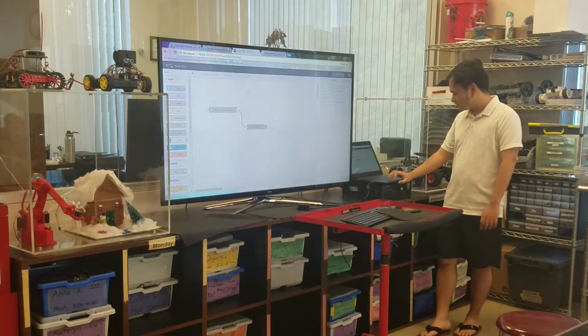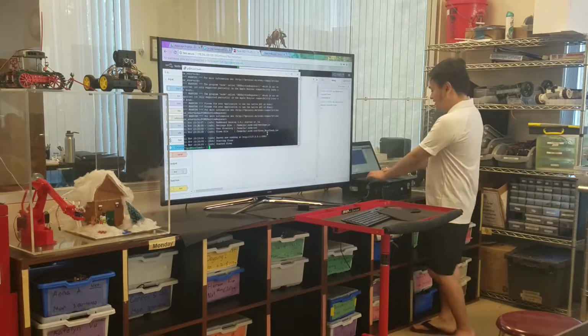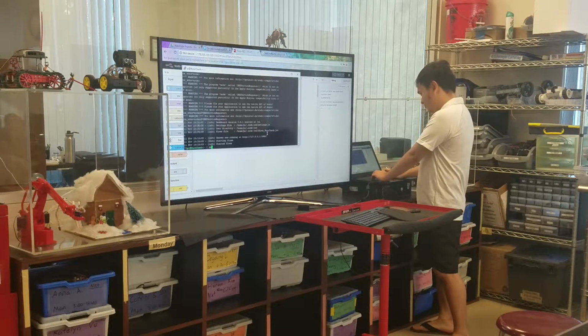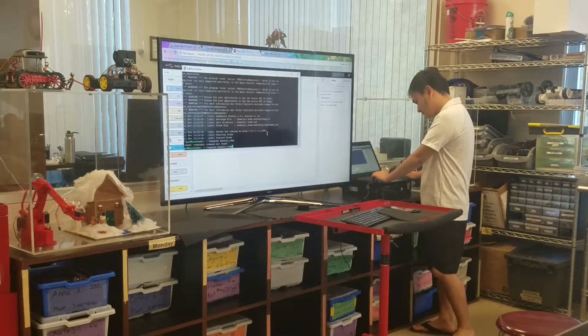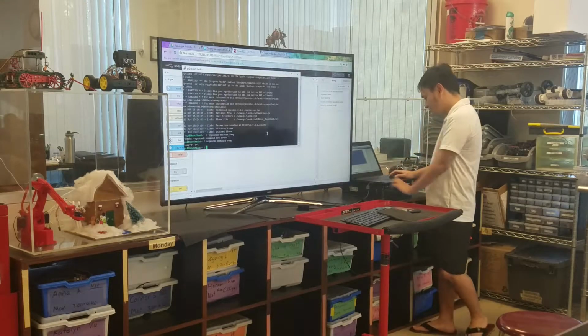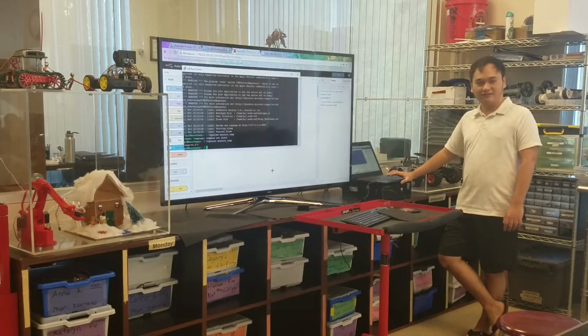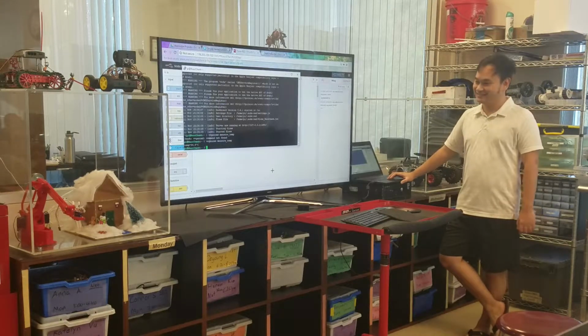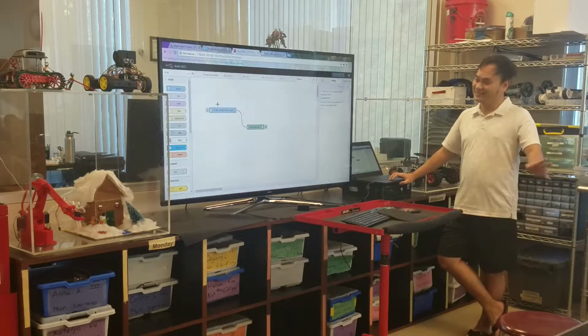Yes. All right. For example, one way you can check your Raspberry Pi temperature: you guys can type in this vcgencmd command, measure_temp. It's gonna show you the Raspberry Pi temperature right now, as you guys can see in the back. It's 44 degrees. All right, and you can access that in Node-RED. Why in Celsius? Because it's international. Just kidding. It's fine.